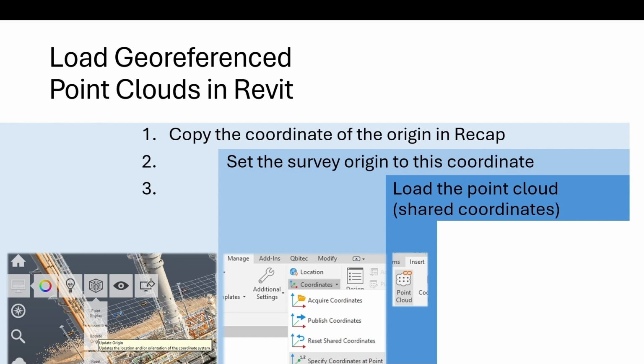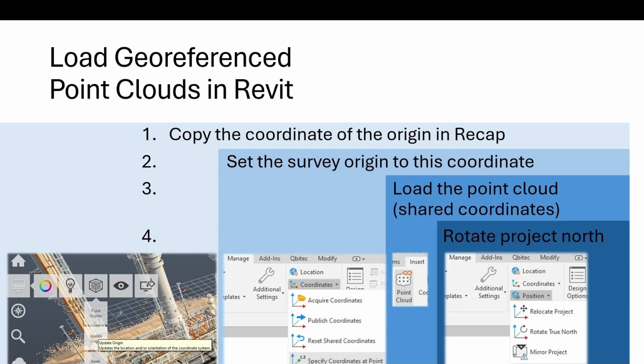In order to rotate the project coordinate system so that the X and Y axes follow the building axes, we select the Rotate Project North option. I would like to demonstrate that.